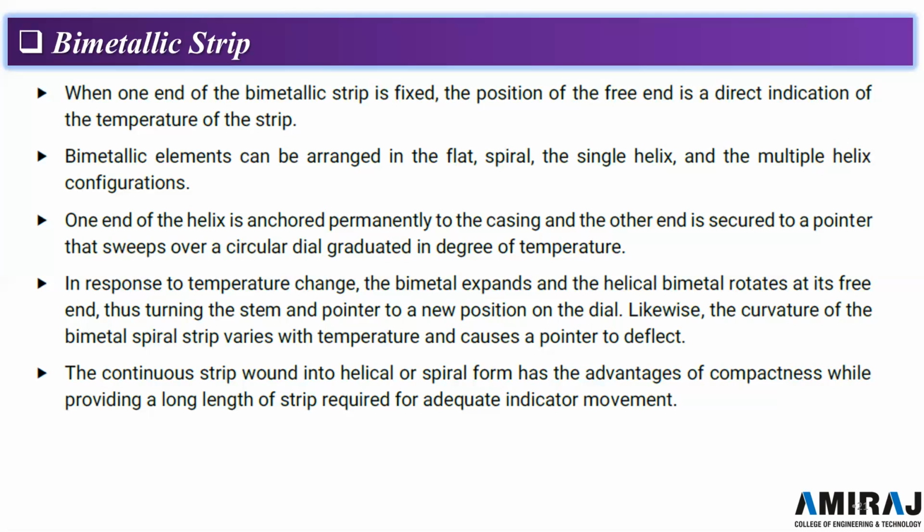A continuous strip wound into helical or spiral form has the advantage of compactness while providing the long length of strip required for adequate indicator movement. So this is the description of the bimetallic strip as I explained earlier.